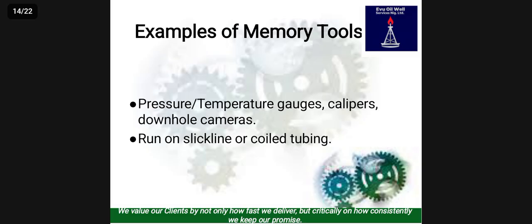Examples of memory tools. Memory tools include the pressure temperature gauge, the caliper tools, and the downhole cameras. These can run on Slickline or coil tubing and store information for later download. They are your go-to tools for non-electric simple data runs.